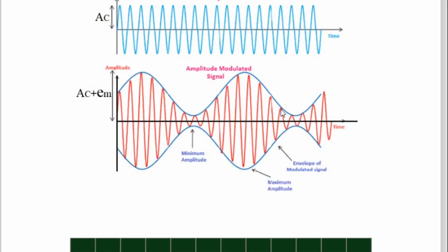And in this way here, you can see this diagram very well, in which the arrow is marked and it is called the maximum amplitude here in the negative, maximum amplitude here in the positive. So here, this is the maximum amplitude. Now, when we join all these positive peaks, we will get our information signal. And there are two side bands in case of AM, upper side band and lower side band. Both side bands carry the information.